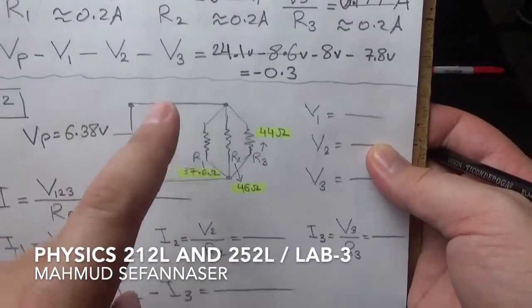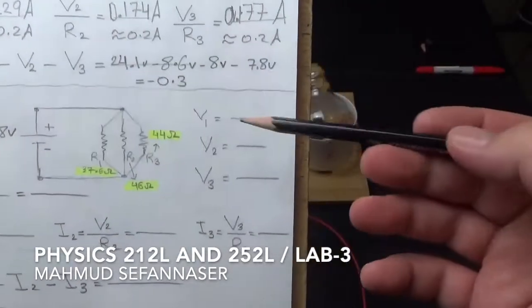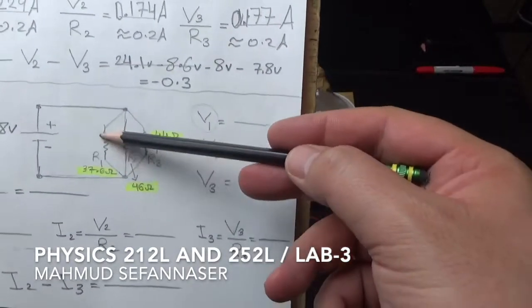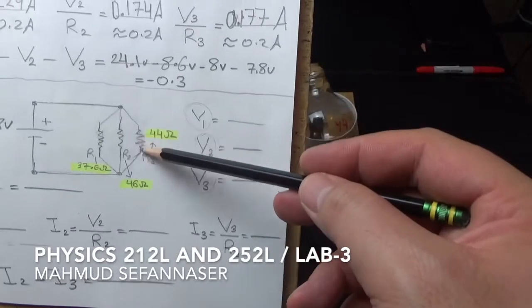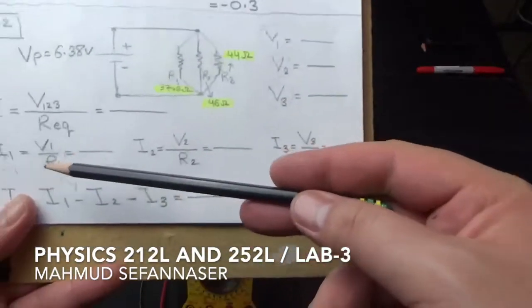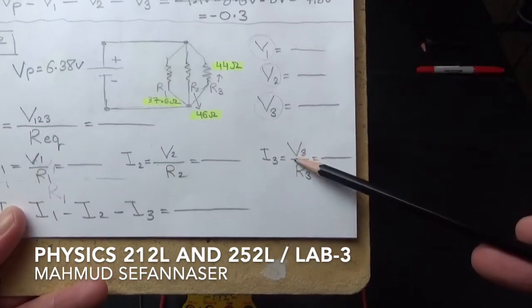So that's great, guys. What I'm going to do now, I'm going to measure the voltage V1 across R1, and then V2 across R2, and then V3 across R3. And then, guys, we will try to calculate I1, I2, I3.